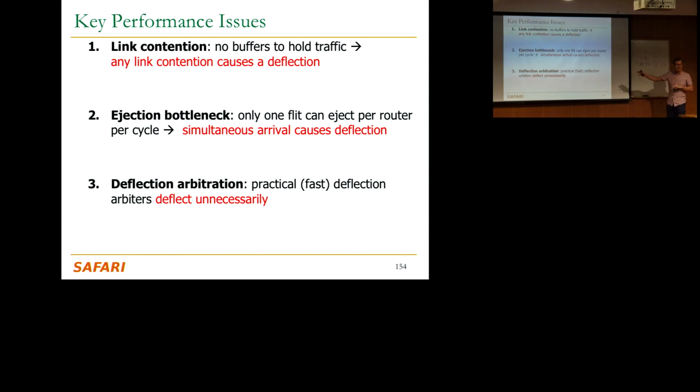If you build a permutation network like we've discussed, sometimes deflection arbiters deflect unnecessarily, right? Because they don't have the full permutation. They have a partial permutation, and that actually makes the router simple, and that makes the router approximate, but that increases your deflection rate. So how do you actually reduce this?